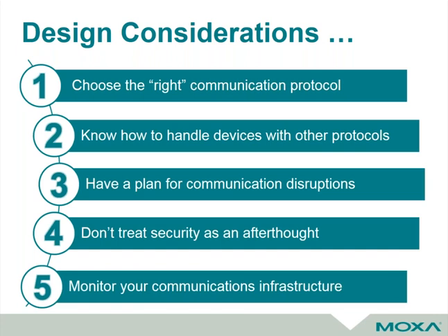And the last one, which is maybe one that's new to a lot of us: don't forget about managed switches. They've come down in price. They're inexpensive today. There's a lot of features that they're not being used for today. There's a wealth of data that can come out of those. Make your managed switches part of your infrastructure, whether you're an OEM machinery designer or a plant manager. Leverage that information to help you more quickly troubleshoot problems. And in a lot of cases, the companies that have adopted this can see failure symptoms before the problem manifests itself. So really good.